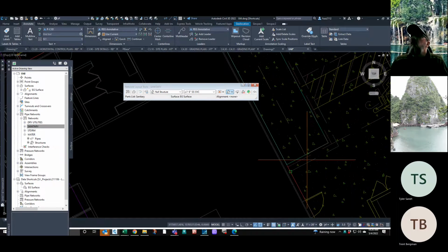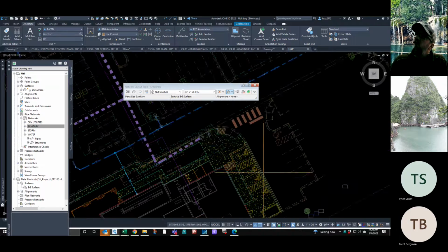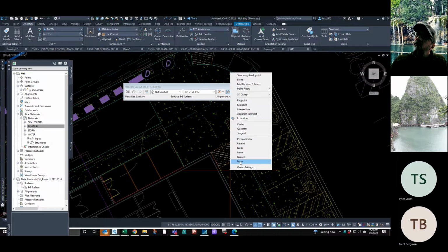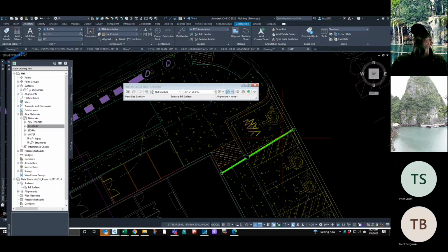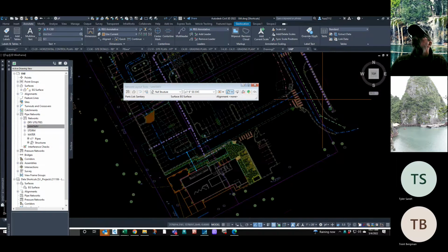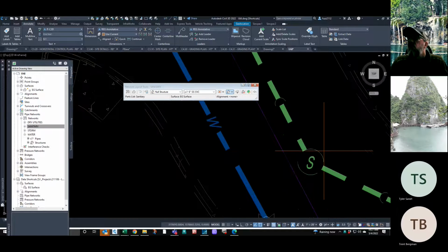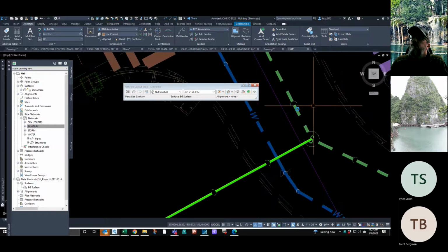I'm just going to draw it perpendicular to this line. I'm going to draw it right here. And then we're going in the downhill direction into this pipe here. Oh, it didn't make it perpendicular. But actually, we can just tie right into this manhole. So we'll just hover over this manhole. That little circle glyph is saying that it's going to connect. We just connect into that manhole.